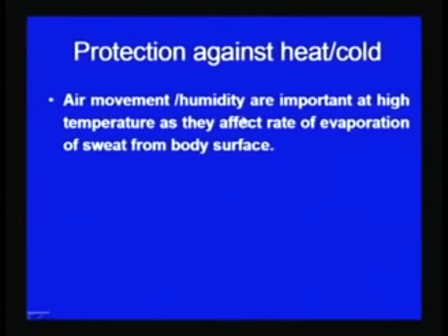Air movement and humidity are important factors that affect the heat transfer, especially at high temperature. They are important at a high temperature because they affect the evaporation of the sweat from the body surface. The higher the air movement, the greater the evaporation, and therefore the body will be able to lose the heat